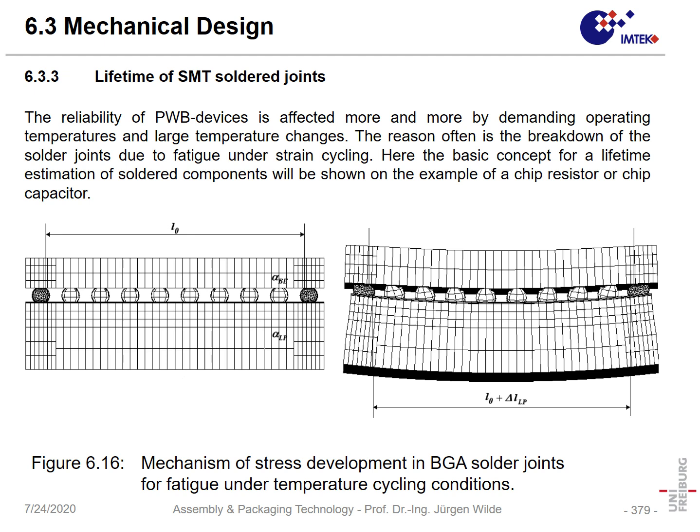Solder joints. When surface mount technology was introduced around the year 1985, people built up assemblies and they started to test these, and they found out that only after a few thermal cycles the surface mounted device just fell off the printed wiring board.